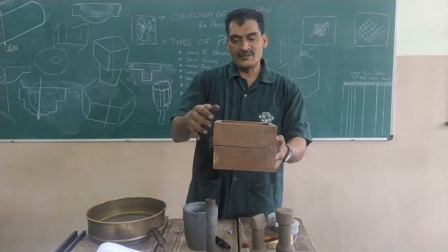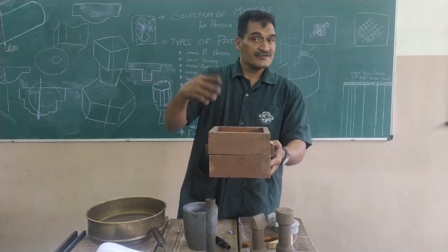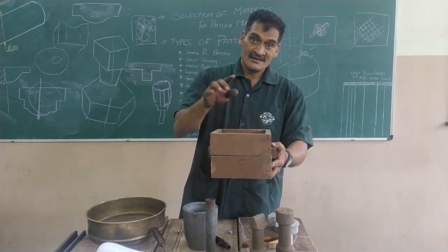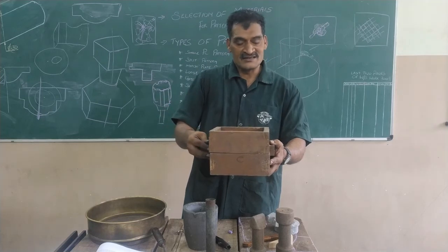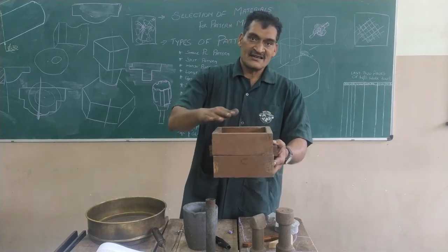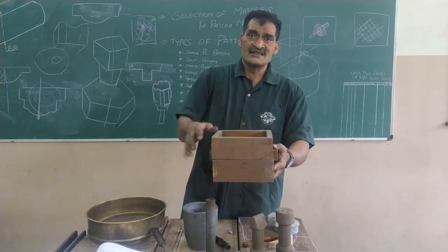After locking with dowel pins, we put in two pins, which we are going to remove later. They are called the sprue and the riser pins. This I will be discussing again later. Then we will be filling it with sand. This time probably not full, just halfway.